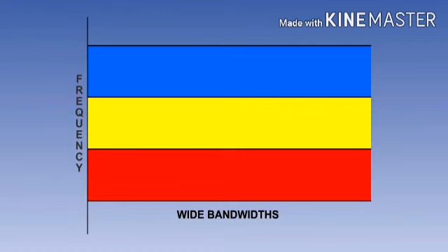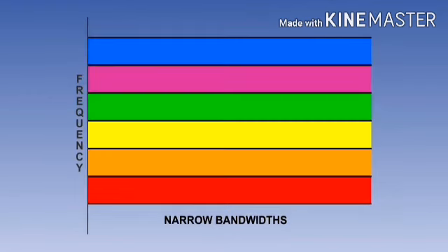In addition to the power saving, it is desirable to reduce the overall width of the transmission because skywaves are liable to distortion in the ionosphere. The narrower the width, the less the distortion and the better the signal-to-noise ratio. Because of the demand for radio frequencies in the MF and HF bands, there is an international limit upon bandwidth of 9 kHz in AM sound broadcasting. So, using narrowband transmissions increases the number of channels available.